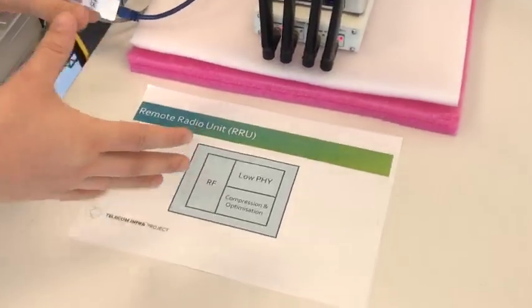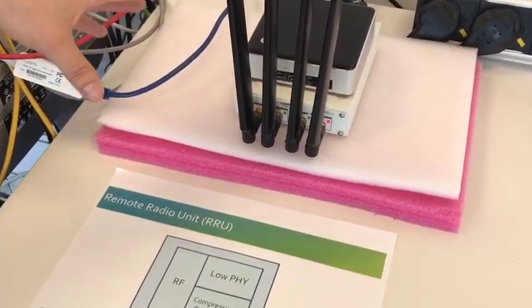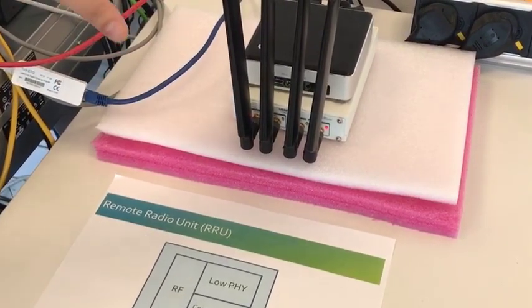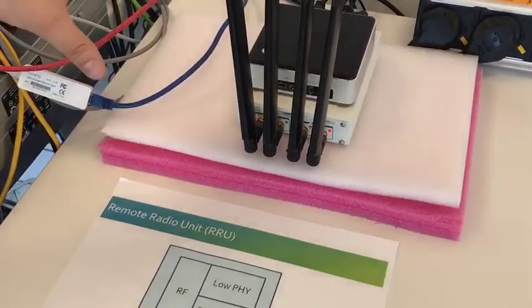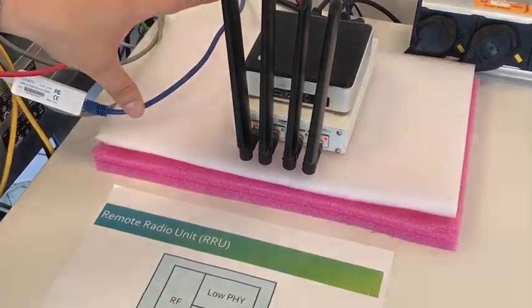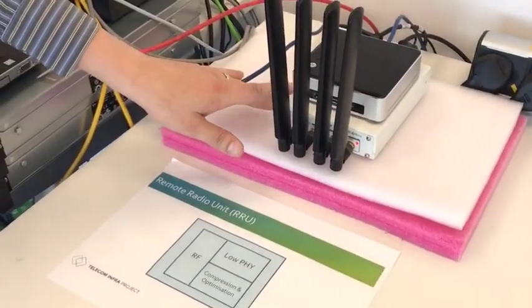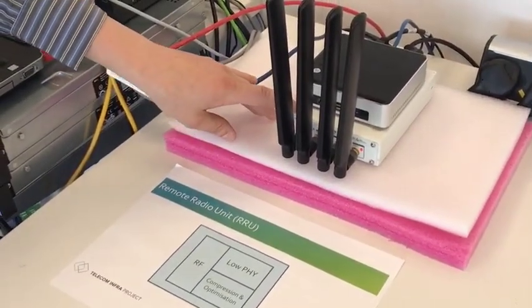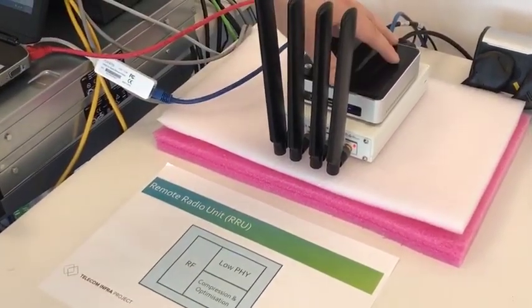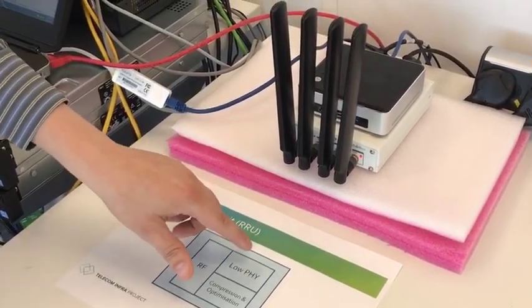And then the final part of the vRAN solution is the remote radio unit. This unit here is not a commercial product, but it's very good for prototyping, and the next things that are going to come into the lab are two different vendors producing commercially ready RRUs. But what we can see here is the antennas, and within this box we've got the power amplifiers and filters, and this little box on top is doing the small amount of processing which covers the lower physical layer.